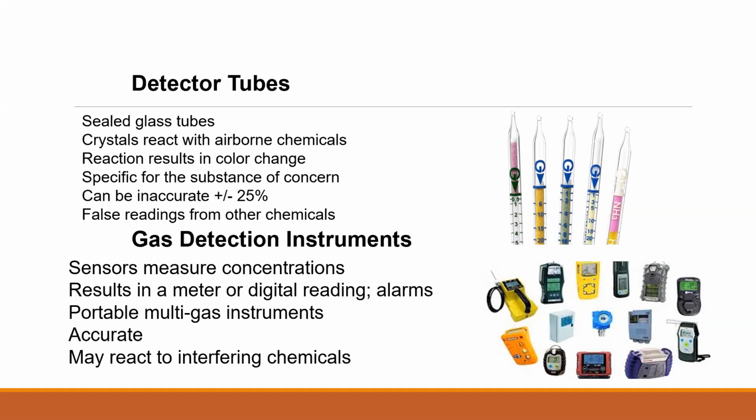But for those people who are working in the confined space, this is the meter which goes with them all the time, remaining on their shoulders or above their pockets. So whenever there is any reduction in the oxygen or in the combustible dust, or an increase in the flammable gas, this detector is going to start beeping. The people working inside the confined space will know that the situation is getting worse, so they can come out easily.